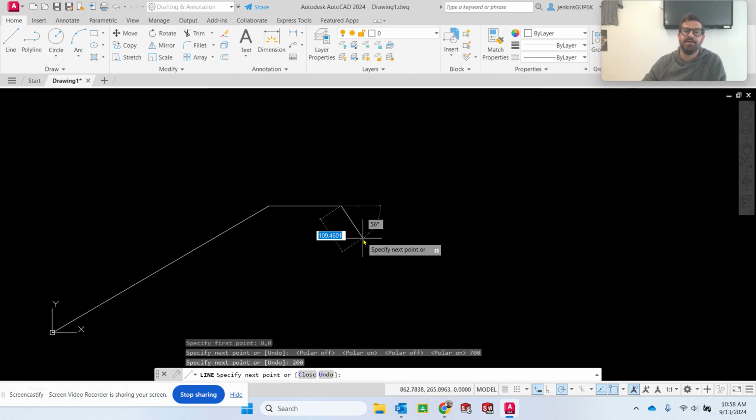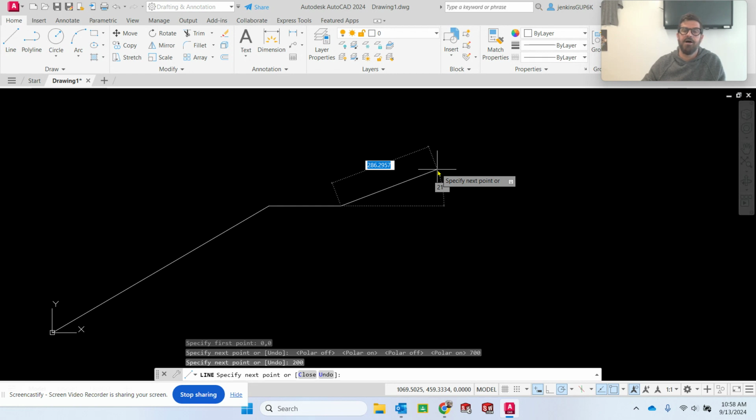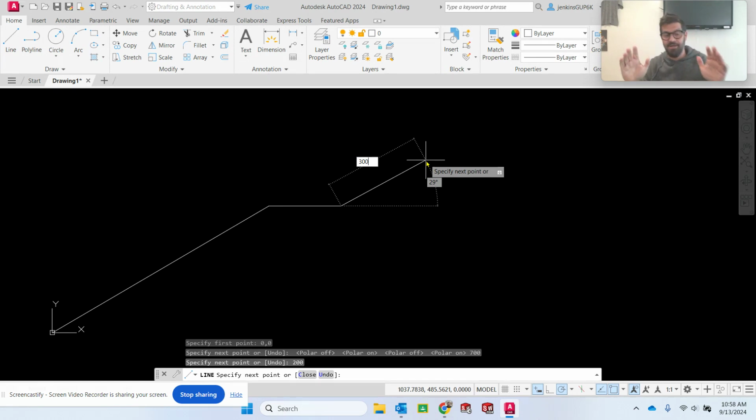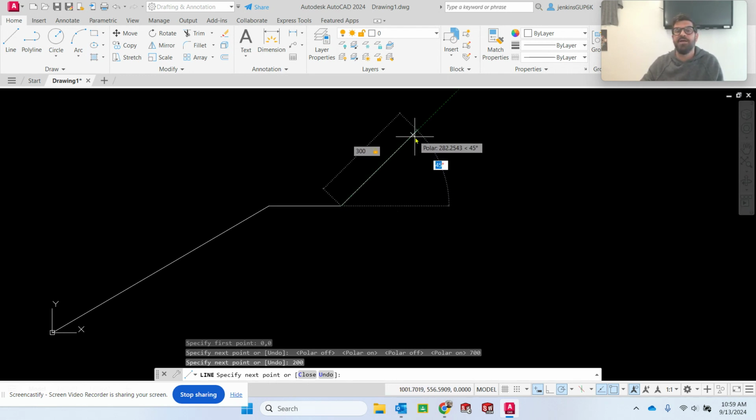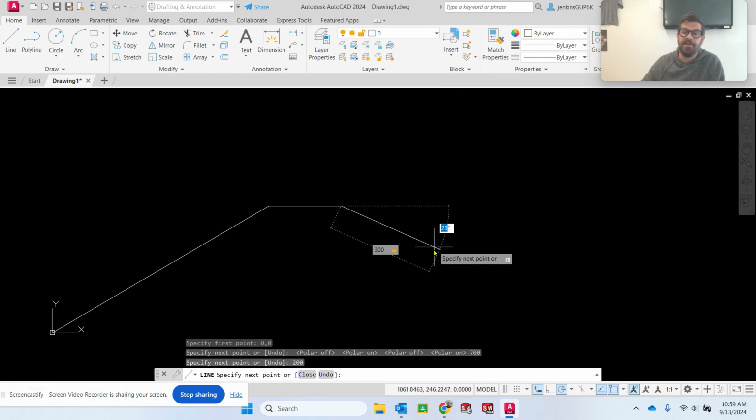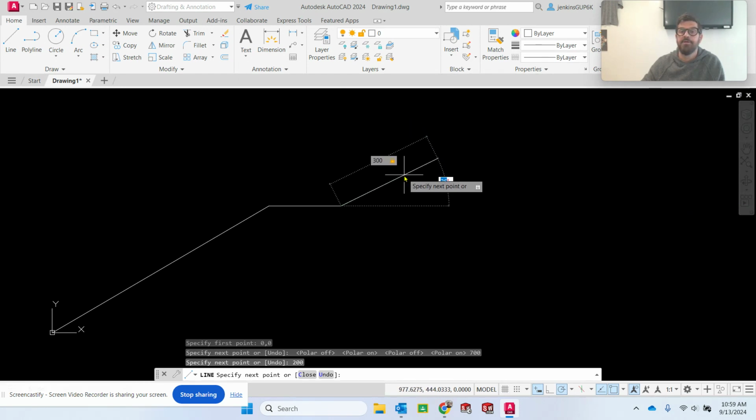Now, I'm going to make a line that goes down. No, let's go up. Let's go up one more time because I'm going to change the angle this time. So I'm going to go up and we'll say 300. Now I'm not going to hit enter yet. I'm going to hit tab and watch what happens. If I hit tab, it knows that I want to make a 300 unit long line, but it doesn't know what the angle is. It's waiting for me to specify what that angle is going to be. So it's keeping it 300, but it's not fixing the angle yet until I tell it what to do because I tabbed over to that angular measurement line.